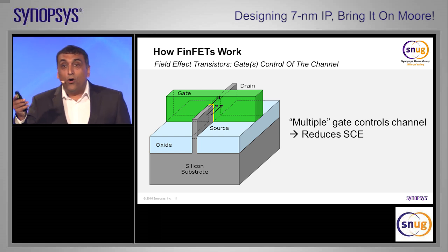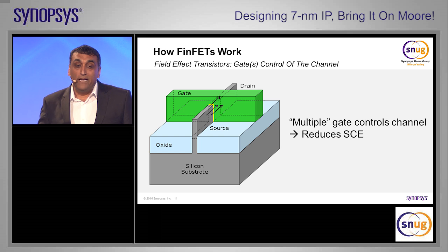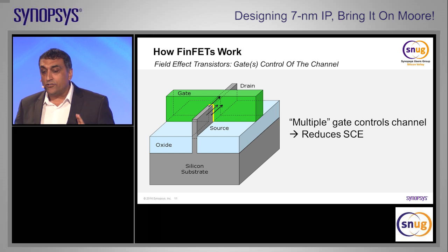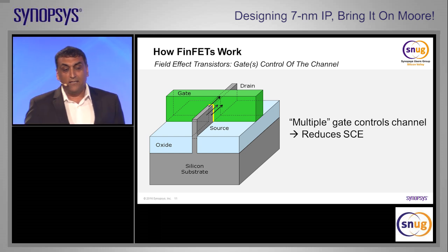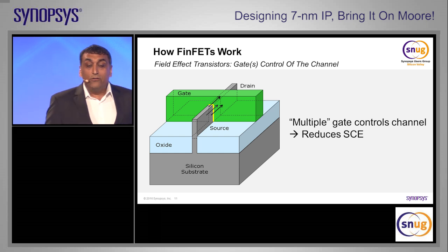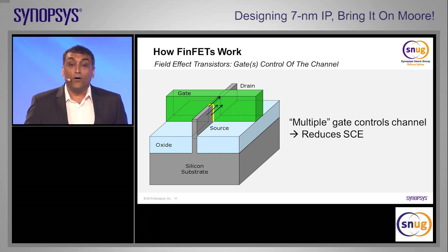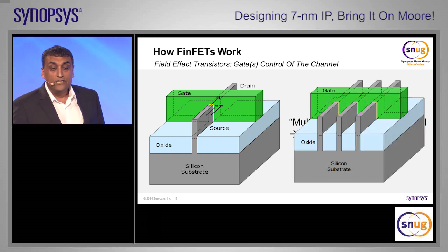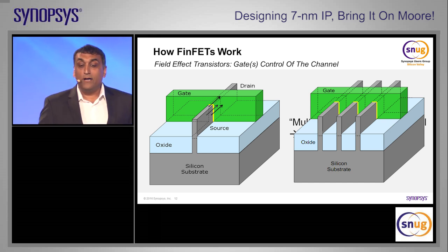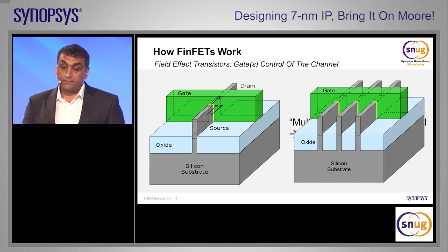You reduce some of the horrible things that were happening at 20 nanometer planar, like drain-induced barrier lowering and the subthreshold slope. Both of these points are related to electrostatics, and I will get into more details in the later part of the presentation. Also, the lower VDD was used to target a lower I-on/I-off. Here you see a complete representation of 3 fins fully surrounded by 1 gate.